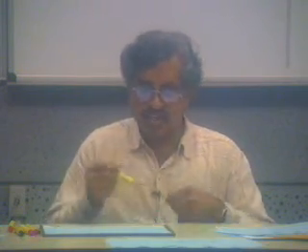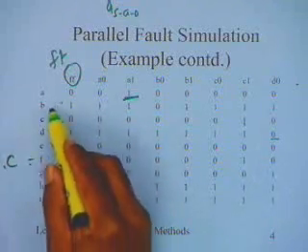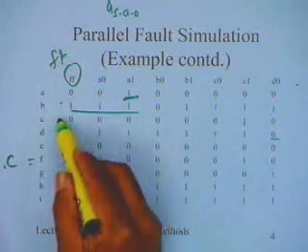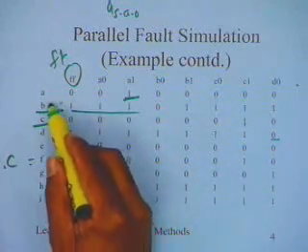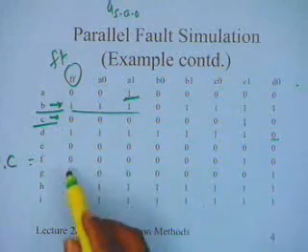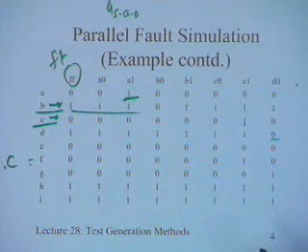In this case it is an 8-bit word, but if it is a 16-bit word, I can AND the whole word bit by bit. So I can actually AND this particular row with this particular row. These two rows can be ANDed together, and I can write the value over here.